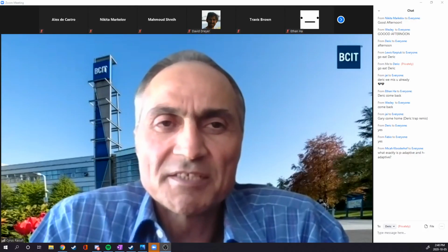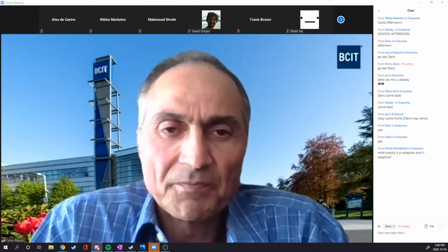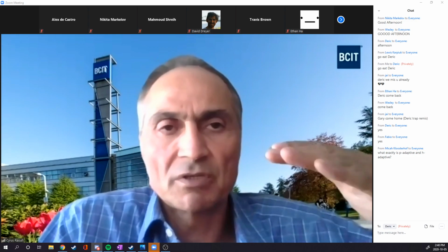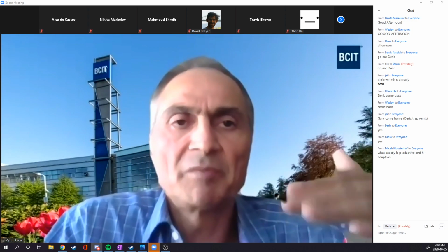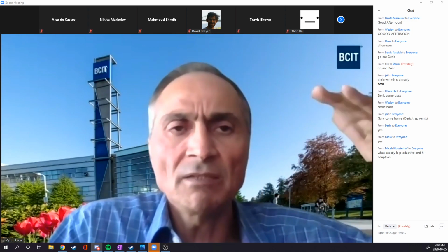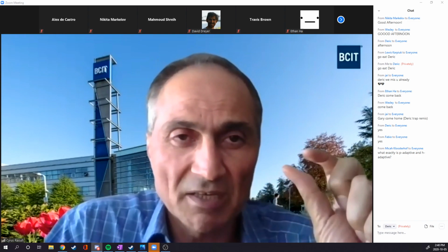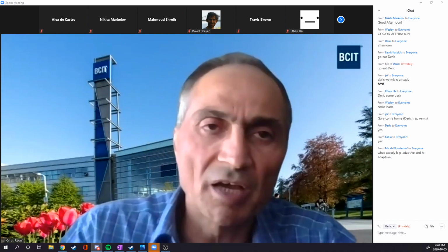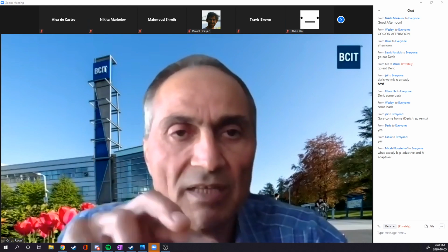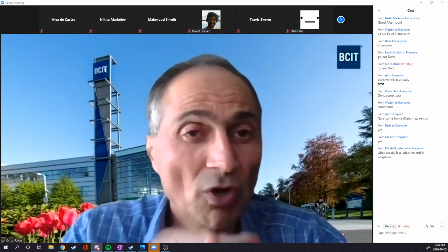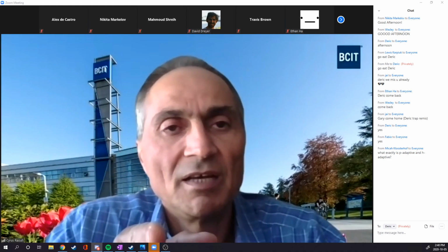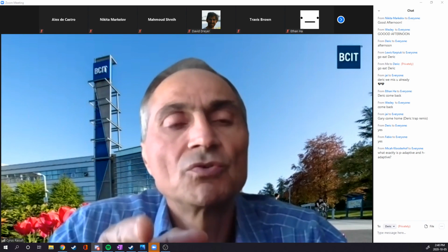and change the size of element. As Nikita says, for example, you are going from 1 millimeter to 0.5 millimeter, then you are going to 0.25, and you can continue reducing the size of element. And every time you have to look at the result and see if the convergence test is done.